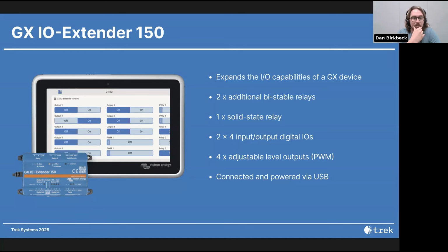The relays themselves, they're pretty limited in their ampacity. I want to say like 2 or 3 amps at most. And I don't think they're configurable from the UI the way that the built-in Cerbo relays are. So right now, as far as I'm aware, the only relay you could use to start a generator would be relay 1 on the Cerbo for auto gen start.